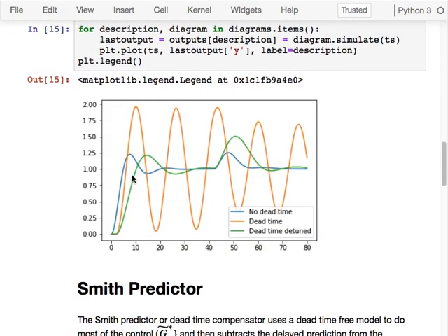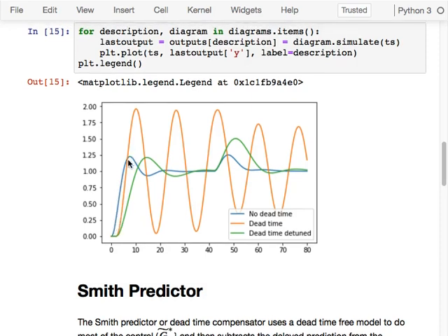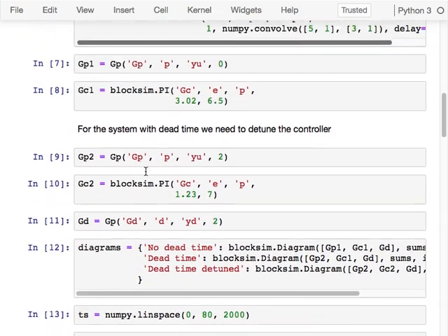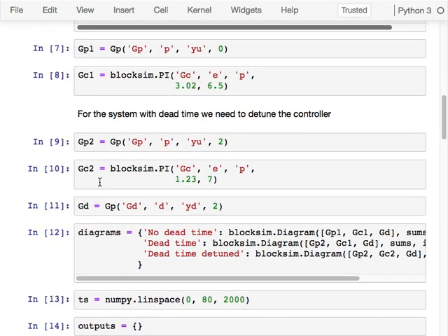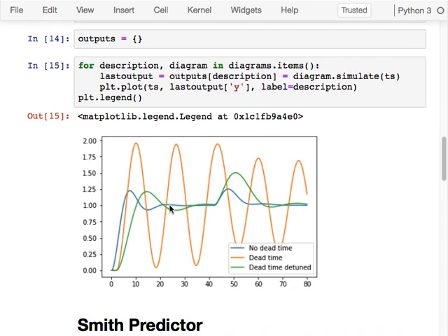And we find that if we have the original system, with exactly the same control settings, the control is very bad. You can see the blue line over here is the original nice tuning. I can't recall exactly how I came across this tuning, but you can see that it has a relatively nice, crisp control response. Adding the dead time, adding that delay, degrades control performance.